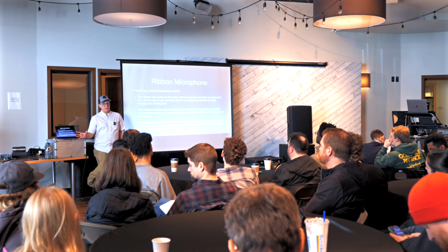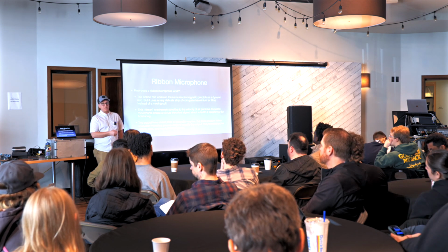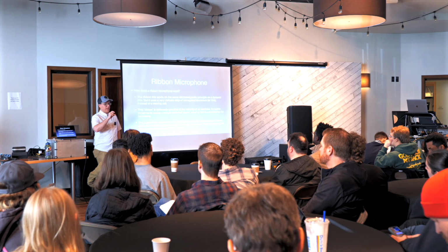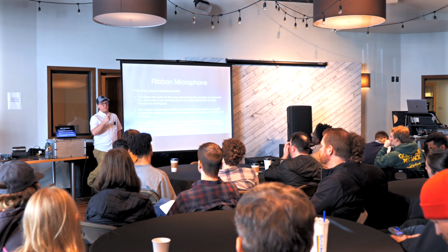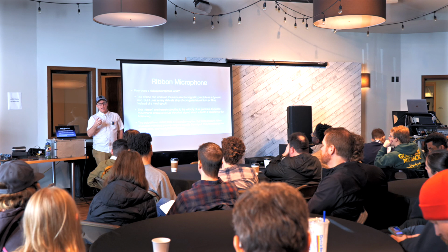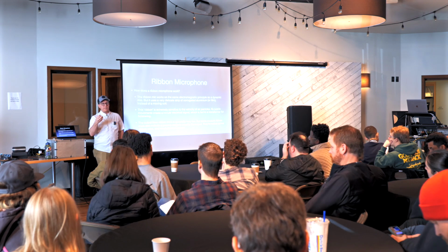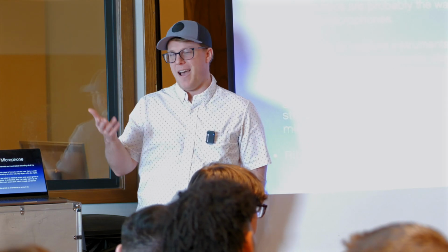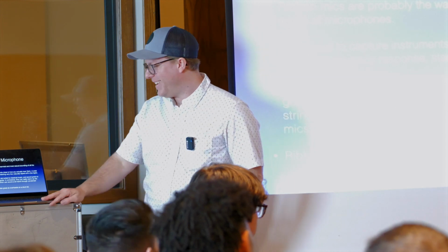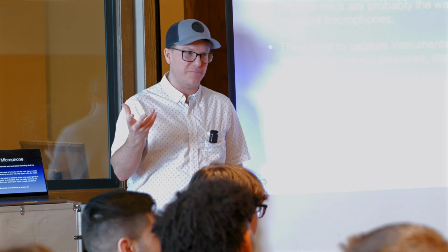Old ribbon mics, if you send phantom power to them, it's going to destroy them because it's just going to break the diaphragm. But most modern ribbon mics have a protector on them, so if you accidentally send phantom power to them, it's going to be fine. Yeah, just don't try it, unless it's an active ribbon mic.